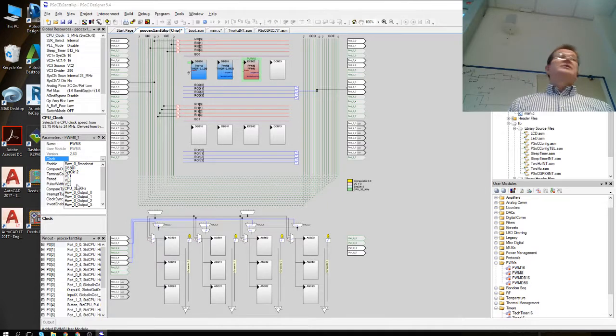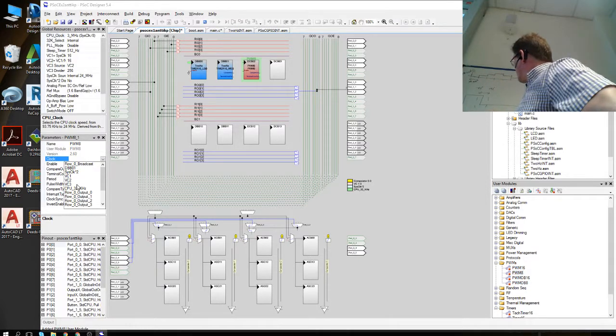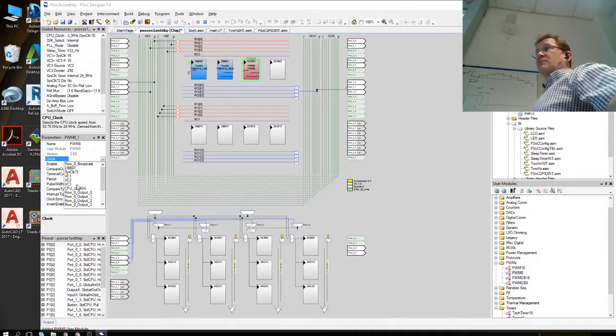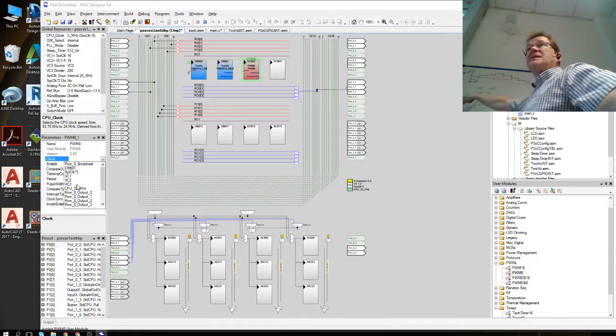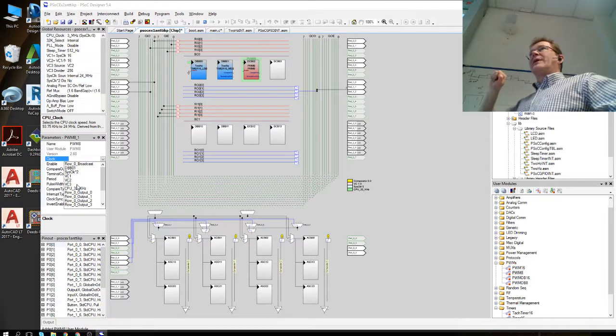It could be VC3, but then you must do the division of those initial clocks accordingly. You can also use the 32K clock if that gives you enough resolution for your system. Remember this 20 milliseconds is roughly 20 milliseconds. It doesn't need to be exactly 20 milliseconds. The pulse width must be exactly, or as close as possible.